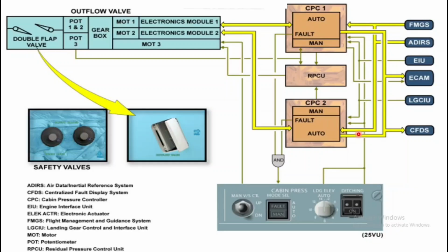The second controller will always be in active standby with automatic changeover after each flight, or in case of failure of the active one. So it will not keep on flying on one computer. Always one will go in rest mode, and the other will take care of the command. So every flight one will change over. In case of failure, it will automatically go to the backup mode.